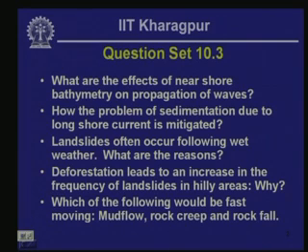The first one that I asked was what are the effects of near shore bathymetry on propagation of waves. As I discussed in the previous lesson, if you have got a protrusion of a landform jutting into the water, and the bathymetry also reflects that kind of onshore or subaerial topography, then that area is going to be affected by refraction and focusing of the wave energy.